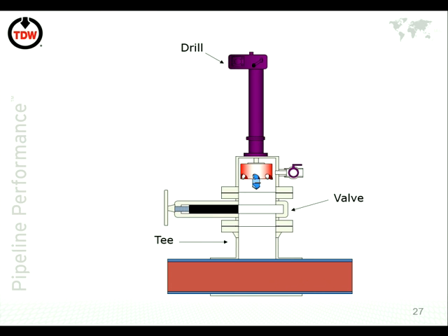This is the cutter. This is the pilot drill, and this is the valve that we would use to temporarily isolate it. So the first thing is we would bring the machine to the point of contact with the pipe. So this is free travel. Nothing's happening at this stage. The drill is coming down through the void in the whole assembly.